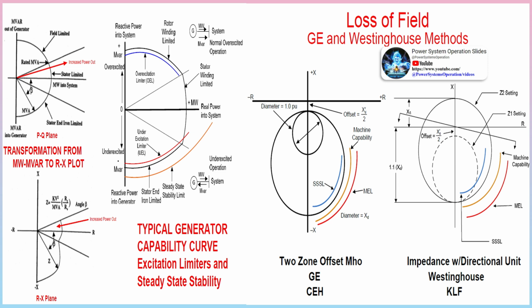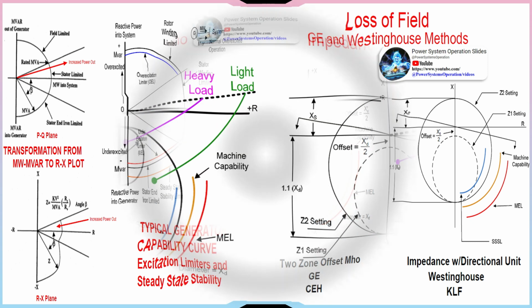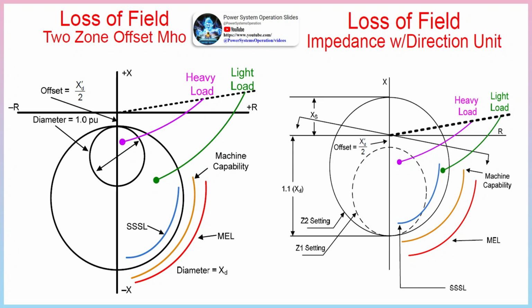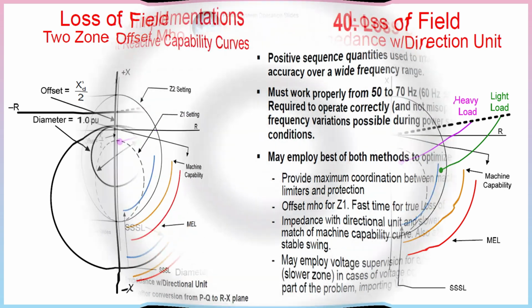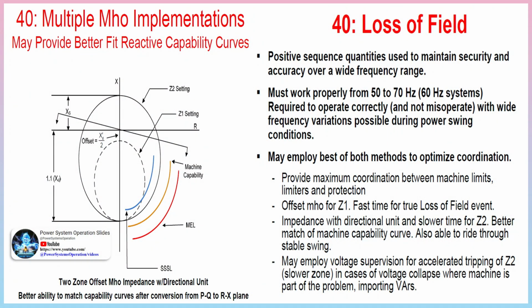necessary to avoid damage to steam turbine generators during rotor pre-warming at startup, necessary to avoid damage to converter start gas turbine generators at startup. In both instances, the generator frequency during startup and shutdown can be as low as 2 Hz. An overvoltage 59 function, designed to work properly up to 120 Hz, is important for hydro generators, where the generators can experience high-speed, high-frequency during full load rejection. Since the V by Hertz during this condition is low, the 24 function will not operate, and the 59 function will provide proper protection from overvoltage.